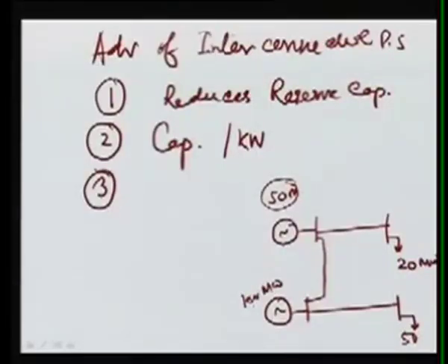The third advantage is that, because you know this load keeps on changing, if the load is very minimum, let's suppose the load has reduced to 20 megawatt here, and for this 20 megawatt we can run only one unit of generation. So it is possible that we can run the most effective unit at the higher load factor, and the inefficient station can be used at the peak hours only. So what will happen? Again, the total cost of the electricity generation will be reduced.